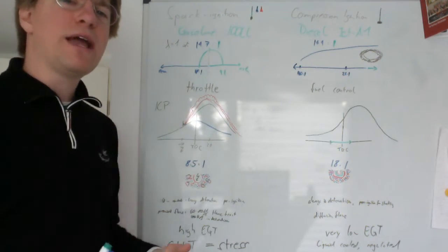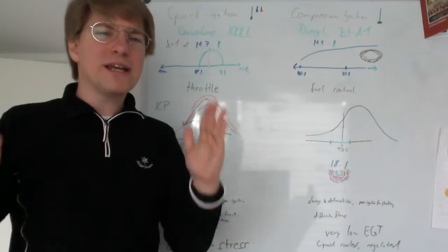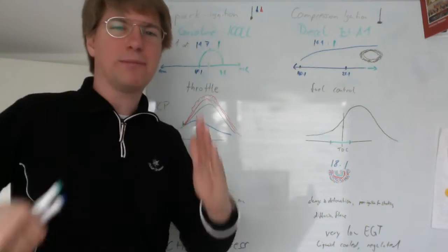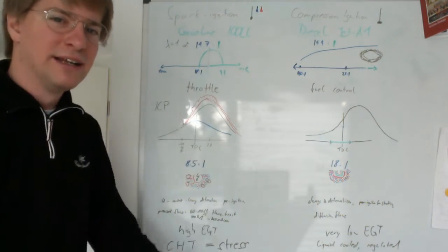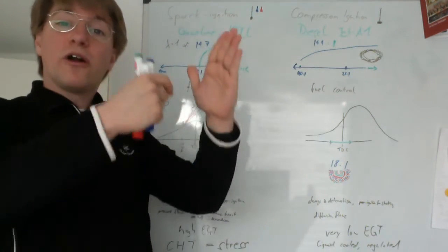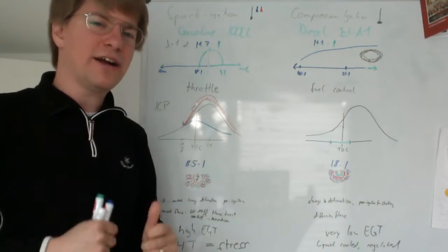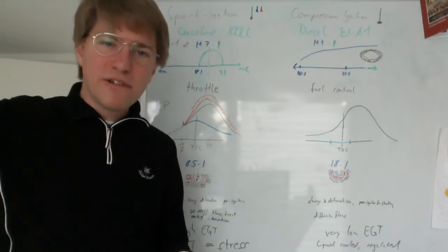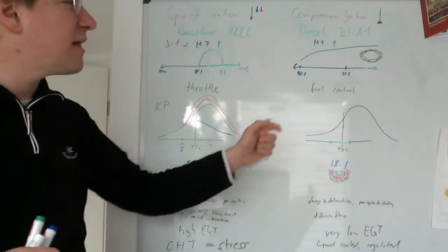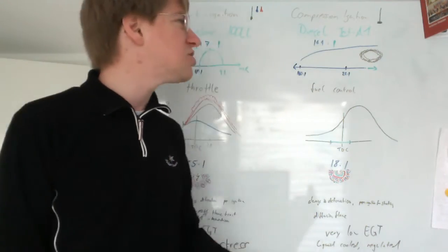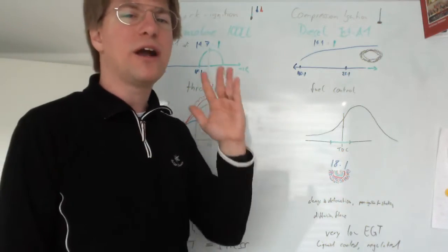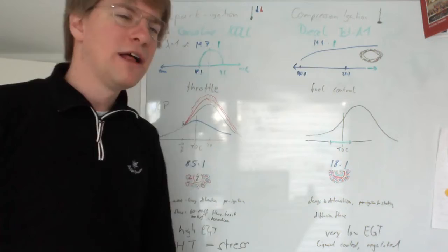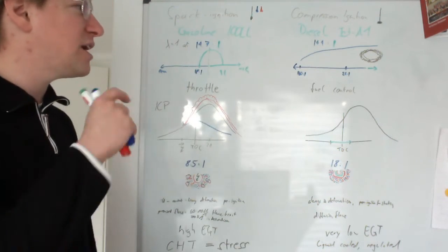So the takeaway point here is that we're always running at 100% volumetric efficiency because there's no throttle plate that we need to suck against. So we're always getting as much air into the cylinders as we can at the given RPM, plus even more with the turbocharger. And that is what makes the engine so efficient, that we always run at the full throttle setting and we can control the power output by mixture ratio alone.